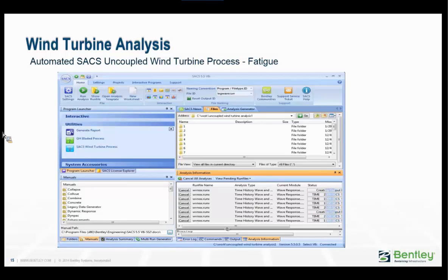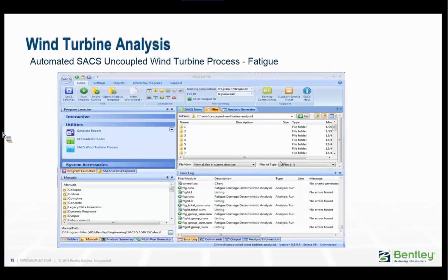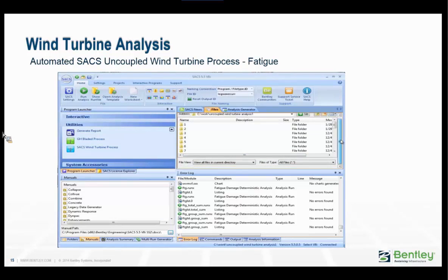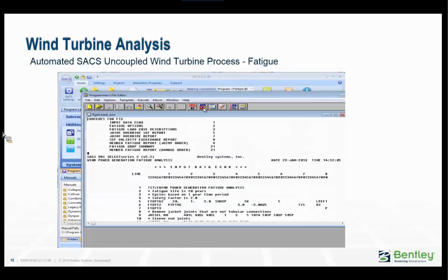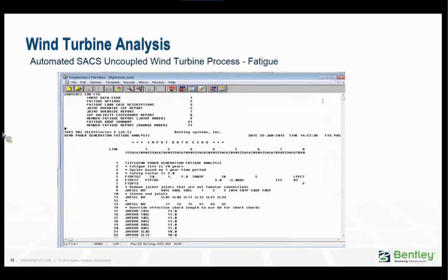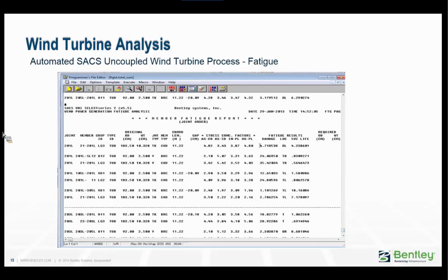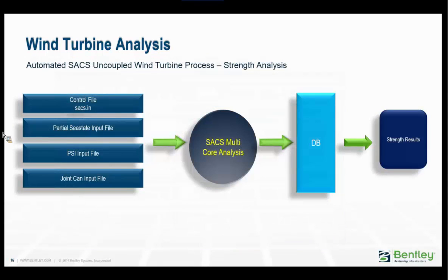So once the analysis has gone through all the simulations, we'll accumulate all the fatigue results and then give you the fatigue life of the structure. Okay, so right at the bottom, there should be a fatigue file, and then basically you can look at the total damage. Here you'll see some fatigue damage results.